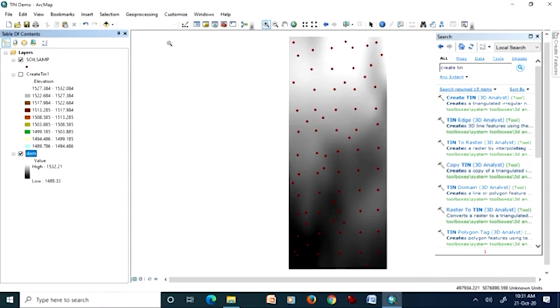So, I could have generated the same points with a DEM covering a large area, but then that means I have created an extrapolated surface, not an interpolated surface. But if I am keeping my digital elevation model within my extent, then it is really under control, and not much extrapolation has been done here.